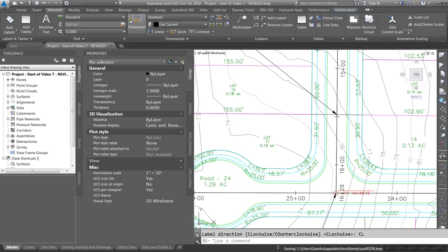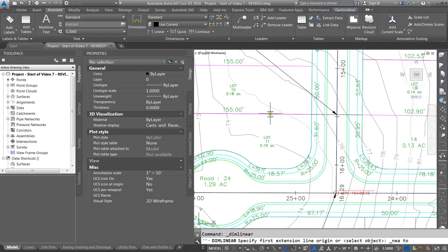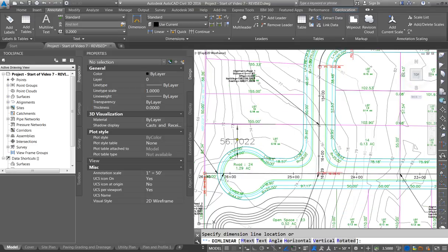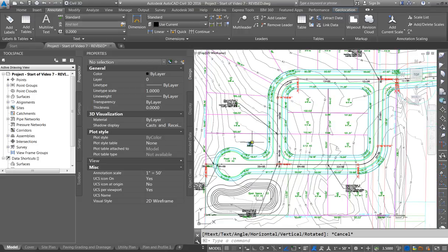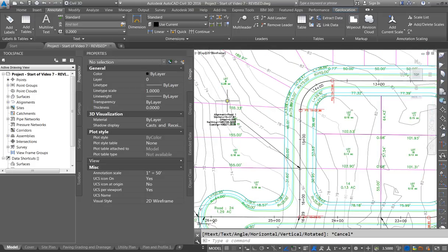It depends. So I'm going to do a distance, and usually most developers, so I'm going to do nearest. Hold on. Most reviewing agencies ask for what the average width is in the center of the lot. So this one's got a 50-foot area here, but it goes down. So we may end up turning this lot into a park area, okay, if we can't fit a house on it properly. Because one of these lots has to turn into park. I haven't set it yet, so this might be the lot to use.